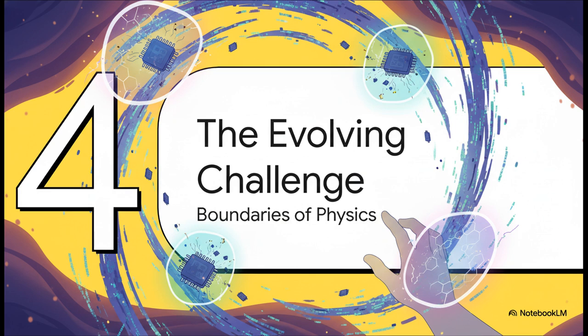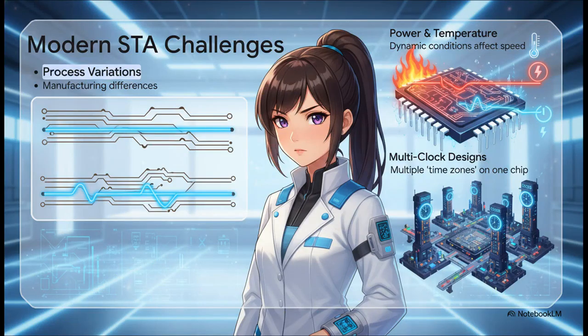Of course it doesn't. As our chips get smaller, faster, and way more powerful, the job of this invisible guardian is actually getting a lot tougher. The challenges are constantly evolving, pushing the absolute boundaries of physics and time. I mean, engineers today are dealing with some incredible new complexities. Tiny variations in manufacturing mean no two chips are perfectly identical, so a timing path that's safe on one chip might be too slow on another. Your phone heating up in your pocket can literally change the signal timing inside. And get this, many modern chips have multiple clocks running at different speeds. It's like a conductor making sure instruments playing to totally different beats still come together in perfect harmony. STA has to account for all of it.